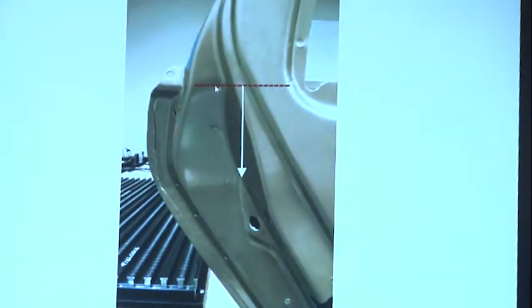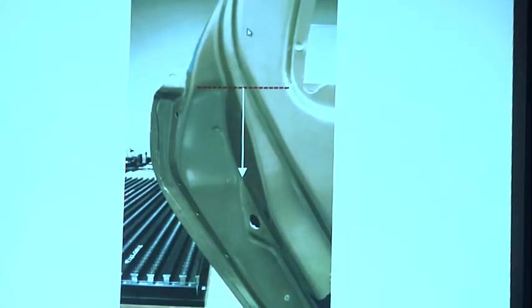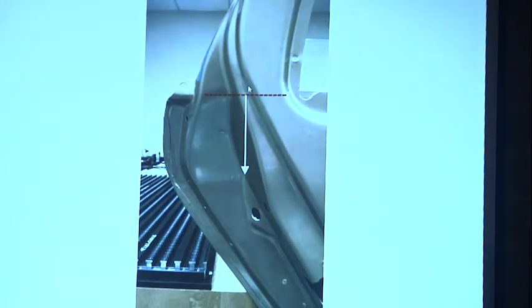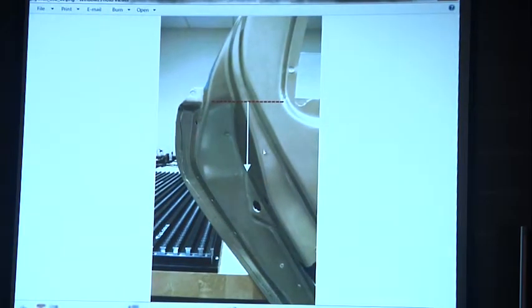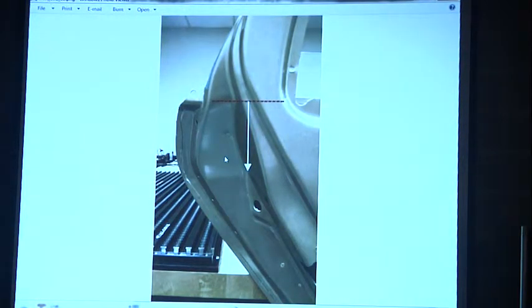So the first quality metric here is a high scanner to surface normal angle, which means, I'll show you what we did in the scan. We did scan using, that's the laser line, we scan using this direction. And this surface is almost normal to the point of view of the scanner, but this one is at an angle.